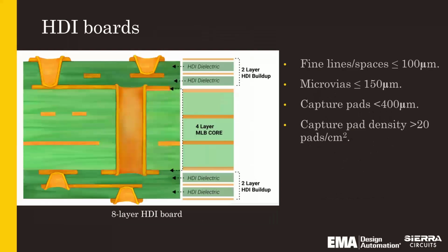And so here's a quick example of an HDI stack up. HDI is suitable for fine lines and tight microvias, those types of things. And you can see, when you pick your HDI dielectric, you have to be especially cognizant of the fact that you're going to laser through those materials.